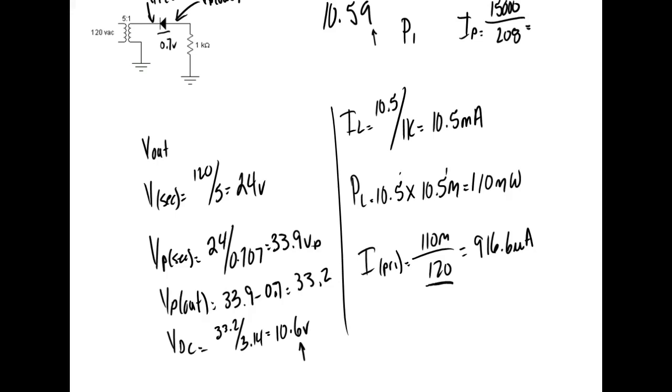So what would be the rated current of the transformer? Times the square root of 3. And why? Because that's a 3-phase. So you probably have to put this in parentheses, guys. Now, if you work with 3-phase all the time, we use 1.73. So it'd be 15,000 divided by 208 times 1.73. There's a lot of things you learn when you deal with electricity, like the square root of 2, which is 1.414, and the reciprocal of the square root of 2, which is 0.707.